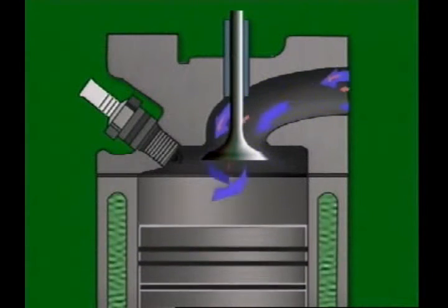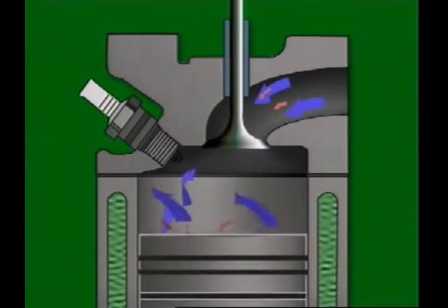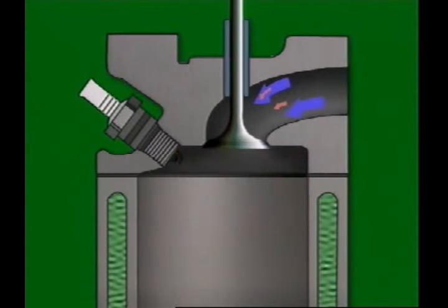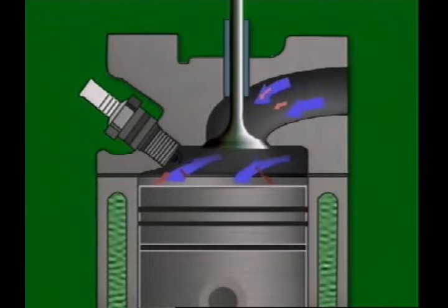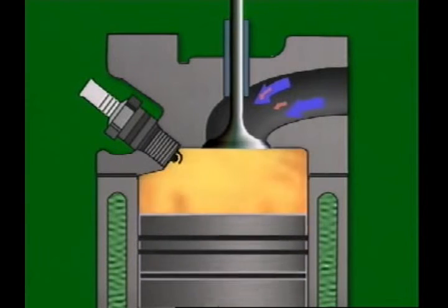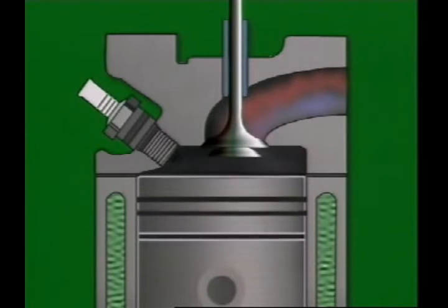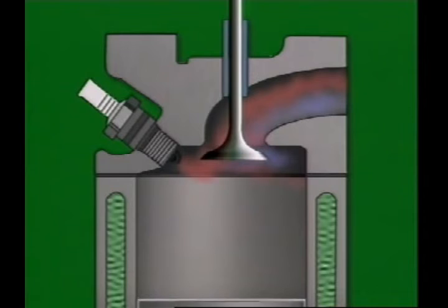Detonation is a violent collision of flame fronts in the cylinder caused by uncontrolled combustion. It occurs after the spark plug has fired. The sudden rise in pressure can cause a knocking sound. Sustained detonations can lift temperatures enough to cause pre-ignition, also called auto-ignition.